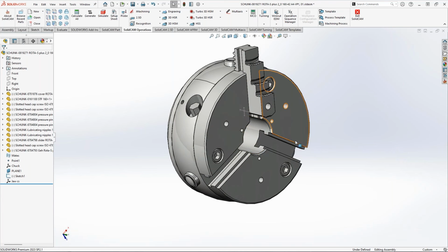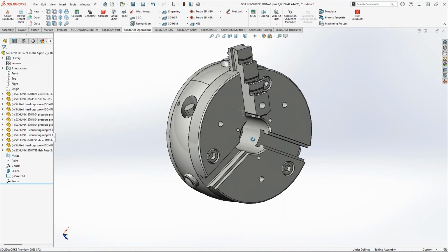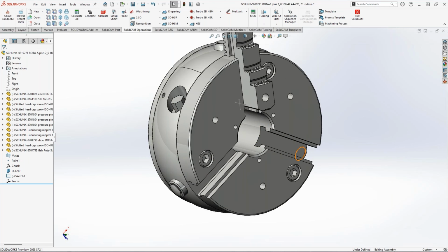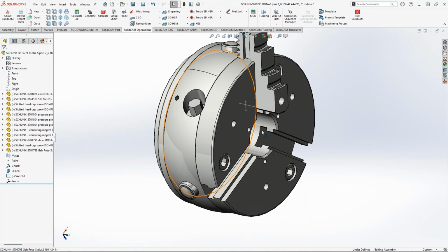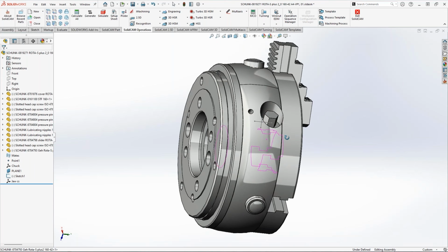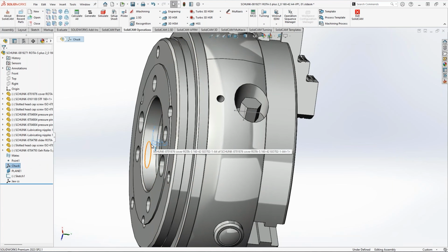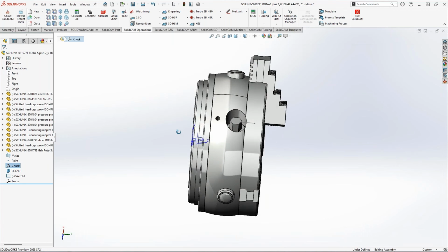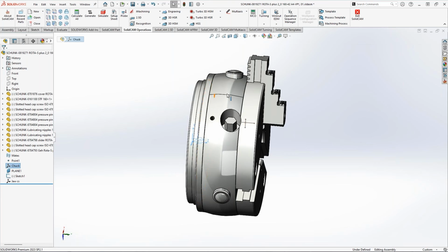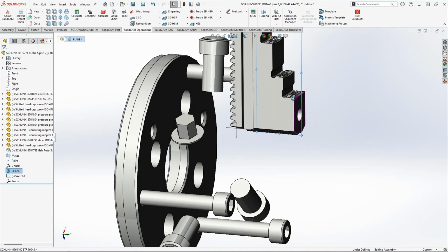In the original one, guys, there are 3 jaws, and for the export, we don't need them. They are there, and I just physically delete them. So everything is kind of ready. I have not done any more work than that. And here I have the chuck coordinate system for the face of it, for the easier export. And also what I have defined, let me just hide this, I have created a plane in the middle of this jaw.